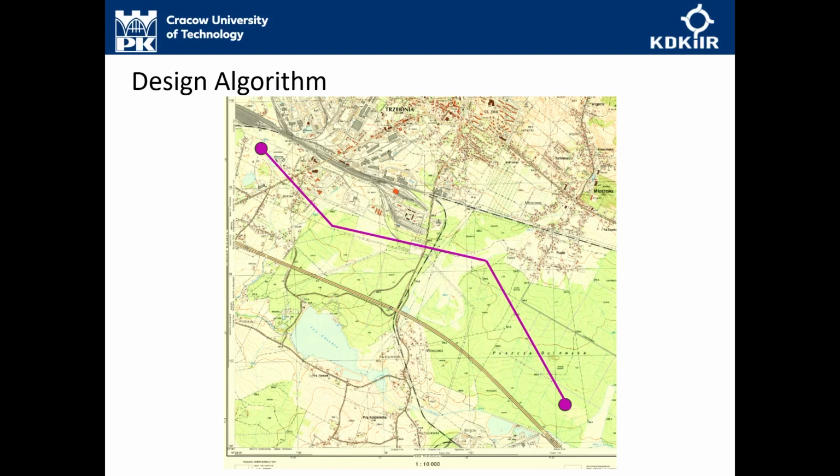The circular curves must be selected based on the parameters of cant and radius that you have calculated. If this is done based on your calculations, we can assume that the railway line route horizontal alignment has been designed correctly in reference to the EN 13803 standard. So that's all.